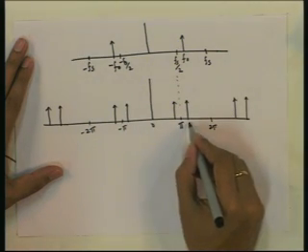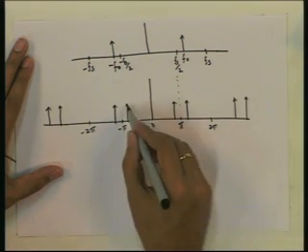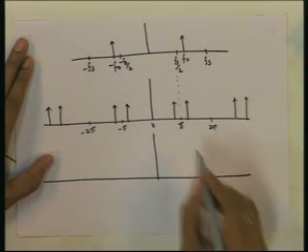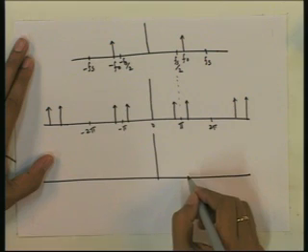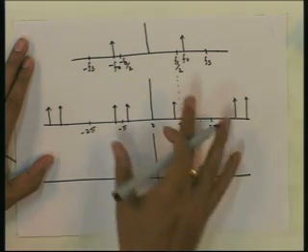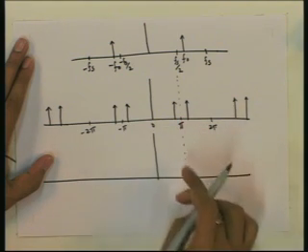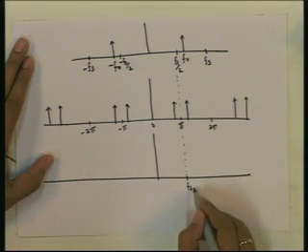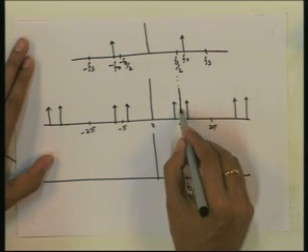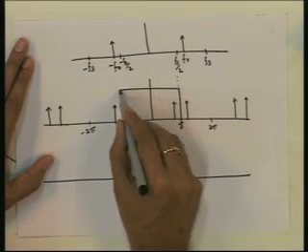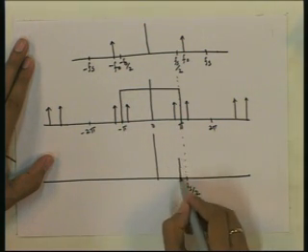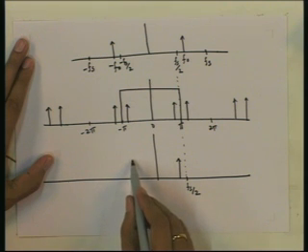And what is the recovered signal? If we recover the signal, again this pi will be mapped back to Fs by 2, because we know that Fs is the sampling frequency. So, we will recover it in such a way that this frequency is mapped to Fs by 2. So, this is Fs by 2. Then what we will get is this part of the spectrum. So, our signal will be like this.